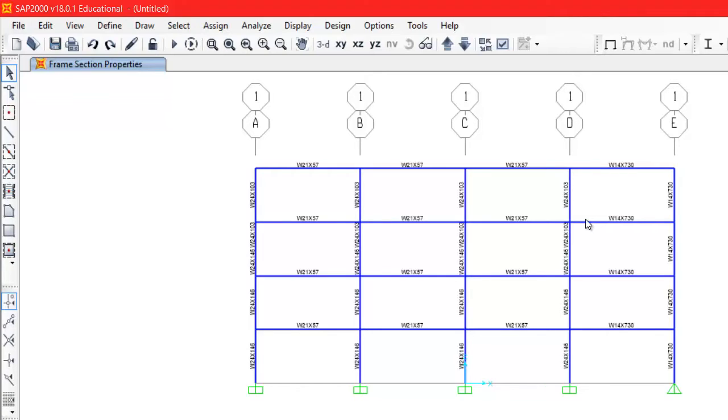But now, yes. For the leaning column and rigid links, we have to set the self weight and mass to 0. This is a different story. We'll do it in a while. I'll show you. So right now we have members connected with rigid links, and everything is elastic, because pretty much every section is assigned this default material, and this default material has E and Fy. It will remain elastic. It's not a nonlinear material.